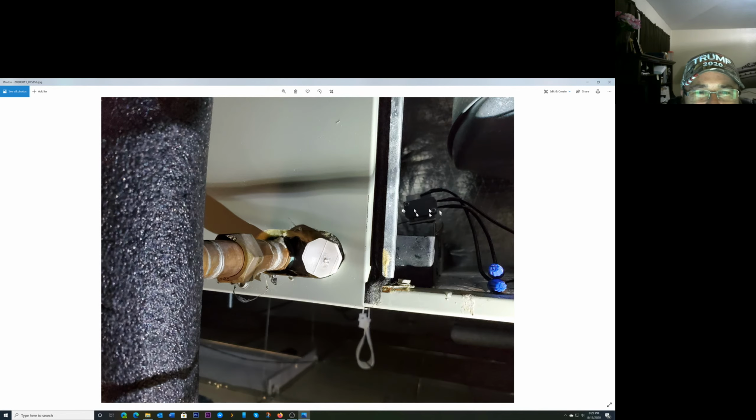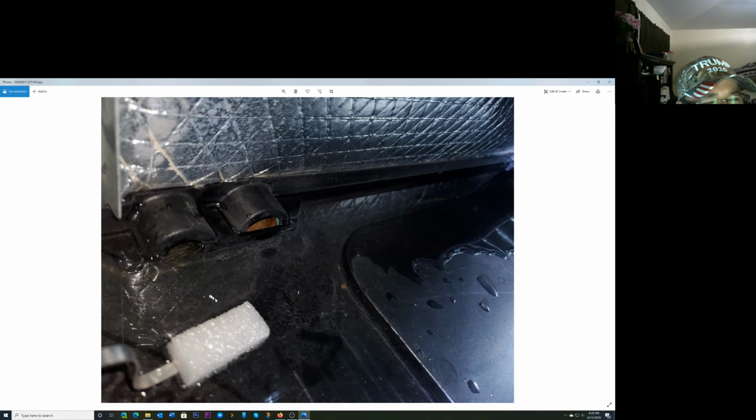You put this little idiot switch in there. It didn't work for some reason, but it leaked. I think the water just pulls it out when the water gets this high. Well, the reason is, I don't know if you guys install these a lot, but you might notice that this right here is the primary drain, and this is the secondary. So looking inside, the water is holding up to this level right here.